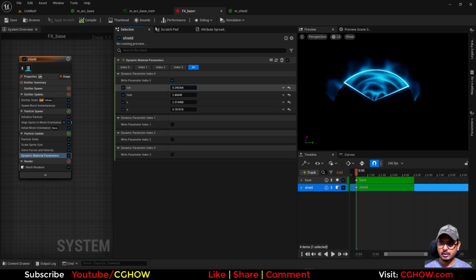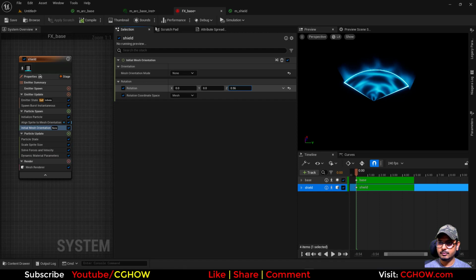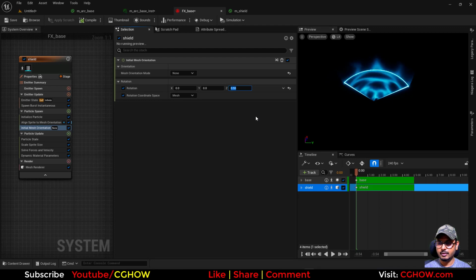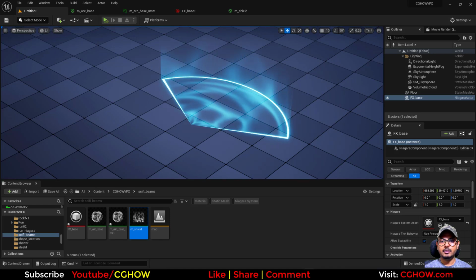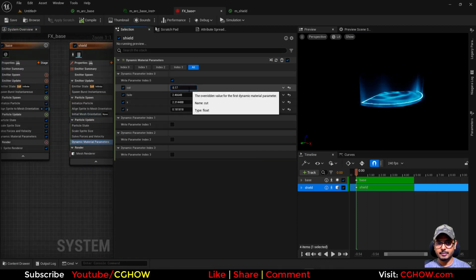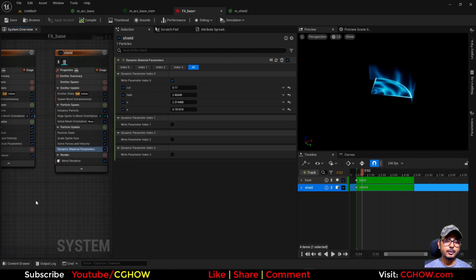Okay, now we will cut it more, 0.175 let's say, and here we'll rotate little more, 0.5, 0.55. Yeah, that's enough. So here in the viewport, you will see both emitters, but there is an issue. This shield, well, first of all, this is still very big. This shield should animate when this opened full, like after 0.2 life.